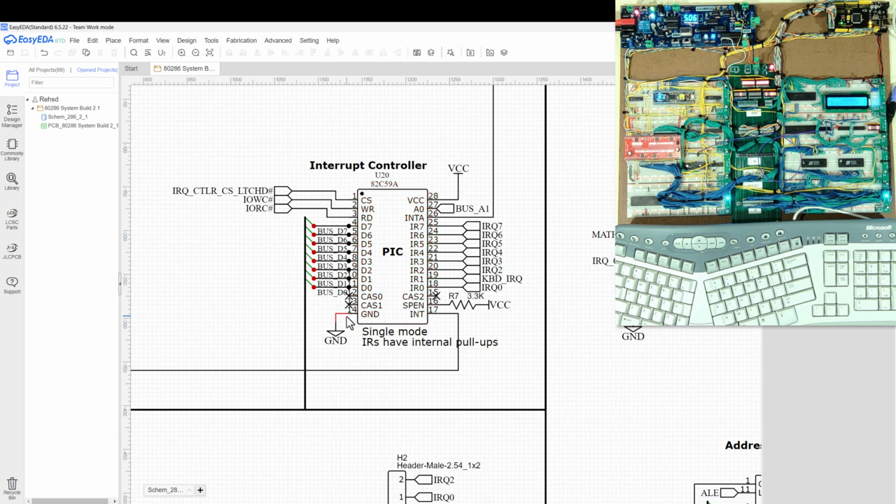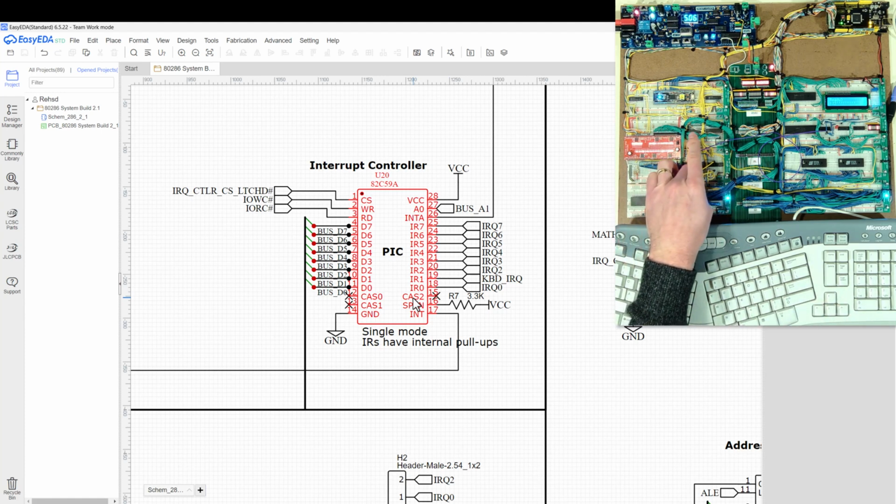So 1 through 14 on this side, wrap around to pin 15. So I was connecting my processor's interrupt to this last pin on the upper right. Well, that last pin on the upper right is actually pin 15, which is CAS2. So it ends up somewhat comically that this PIC has probably been working for a while, but I've been reading the wrong signal coming out of it.